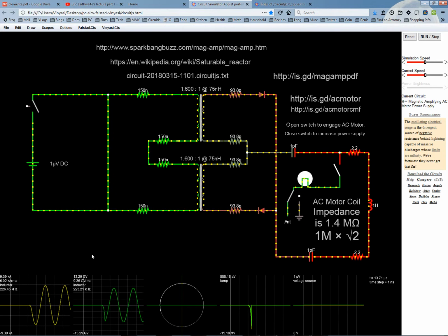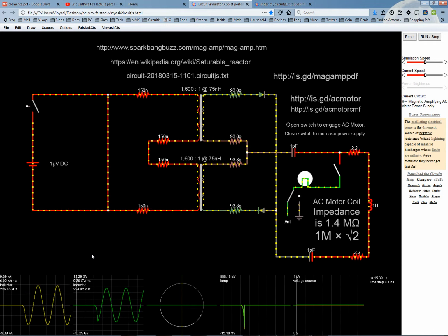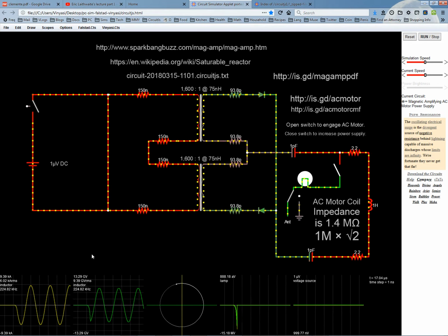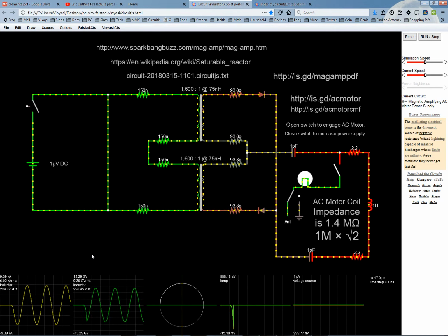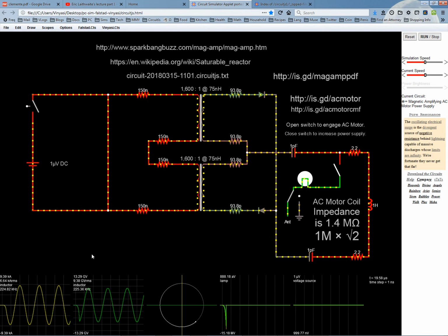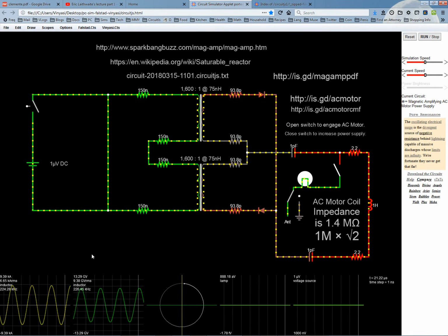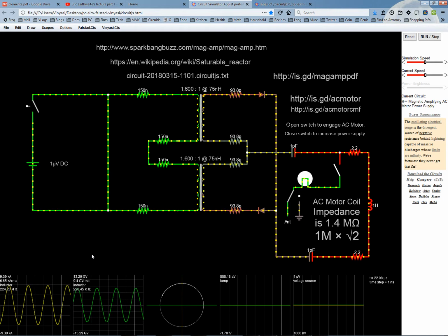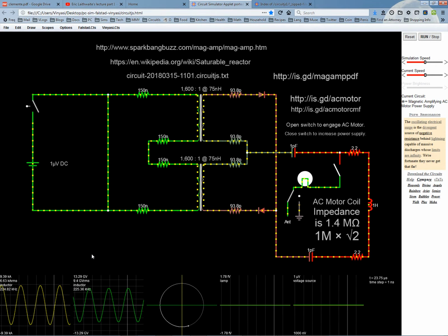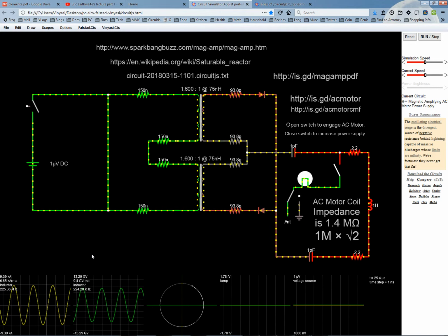I've noticed that in a lot of my simulations, I would try to get the frequency, or RMS, and I couldn't get it, and I didn't know why. Because my output was spiky, densely populated with random spikes of varying amplitudes at varying intervals in time. And so there was nothing for the simulator to average to find out what an average figure of RMS and frequency is in that component. So this is one of the rare instances in which I get a readout of this sort.